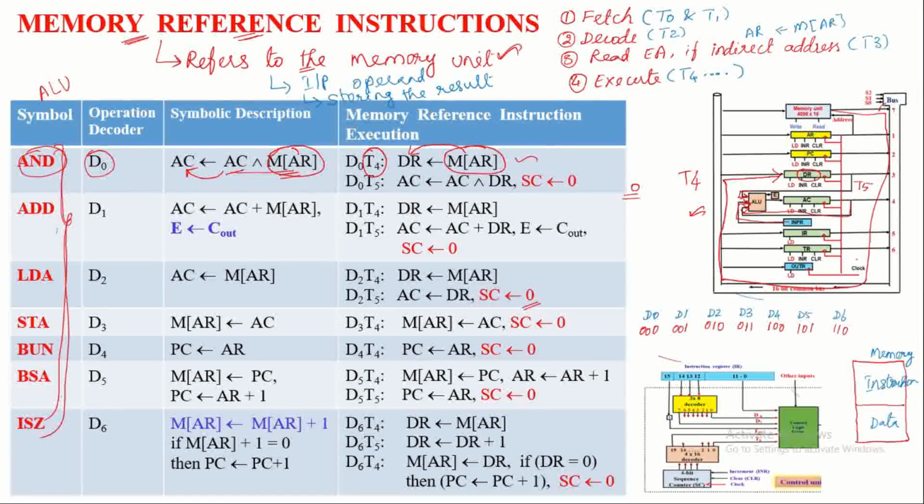The operand or memory word is taken from the memory unit from the location pointed by the address register, and it is transferred to the data register when timing signal T4 is active, the selection signal values are triple one, the read signal of the memory is active, and the load signal of the data register is active.